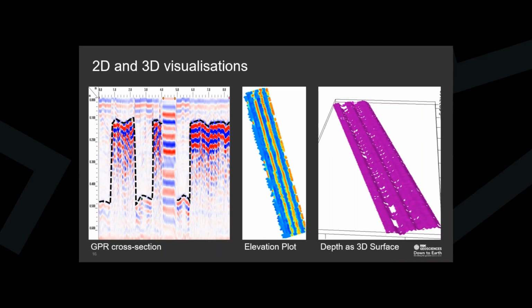The purple chart is a plot of the depth of the base of the bound material, which is the base of the asphalt, essentially. So you can see it quite severely deepened, and then essentially it was just tarmacked over again and again and again, which resulted in localized deepening of the asphalt.